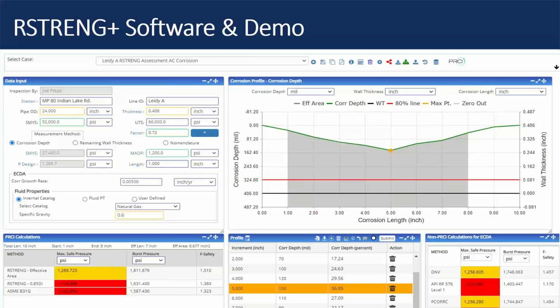The only thing is you hurt yourself by extending some of these intervals. If you keep them short, like many companies are now using 1/2 inch. They were using 1 inch, but they're finding that they get a better assessment by doing 1/2 inch. It may take a little longer if they're doing it manually, but not if they do it with optical imaging, and what I mean by that is 3D laser or 3D structured light.